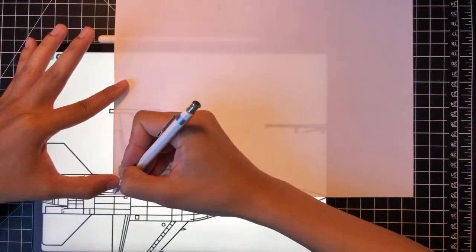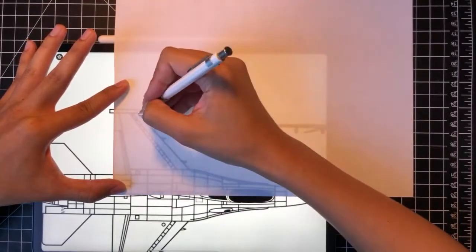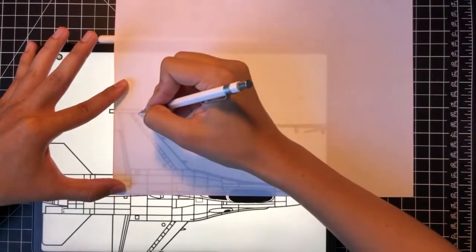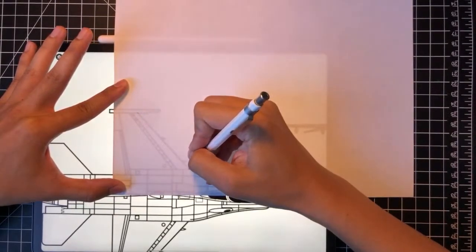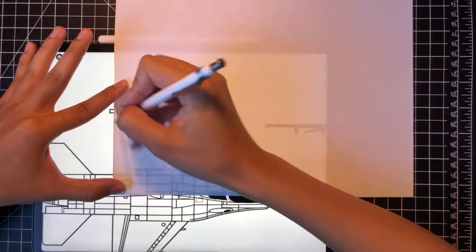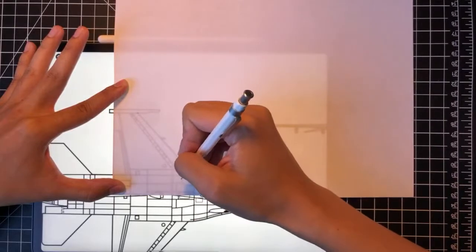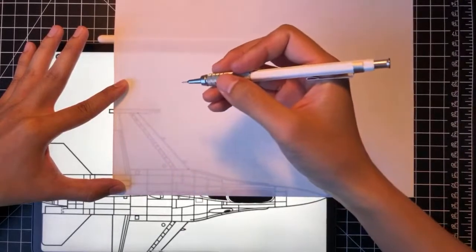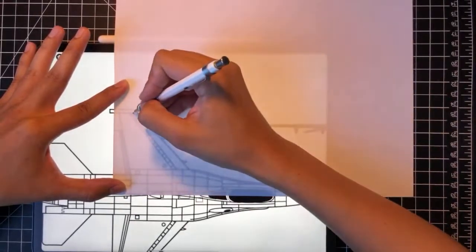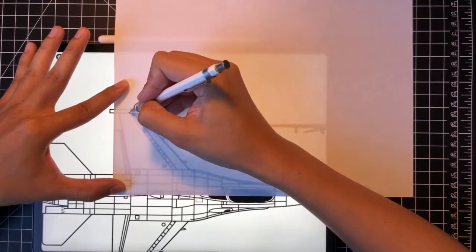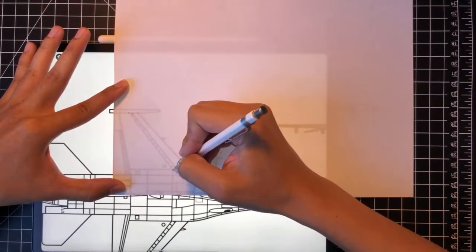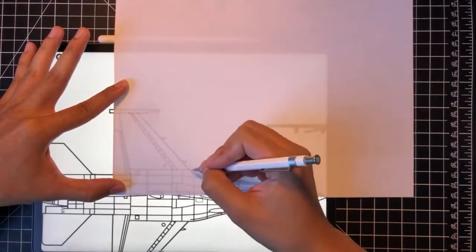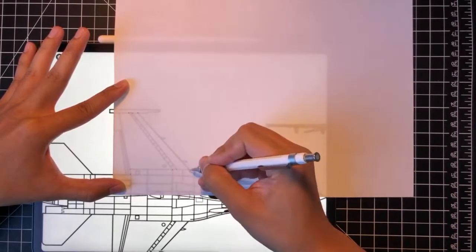They're the result of human-made objects. So we need a little bit of wing to be on the inside of the fuselage. What I mean by that is, again, we need that cantilever, right? Wings are essentially cantilevers. We need a little bit inside to give it that rigidity, right? Because if you just have it attach on the outside, it's not structurally reinforced. So you should look into that and make sure that it is all set there. So this is kind of just outlining where the wing is going to go.